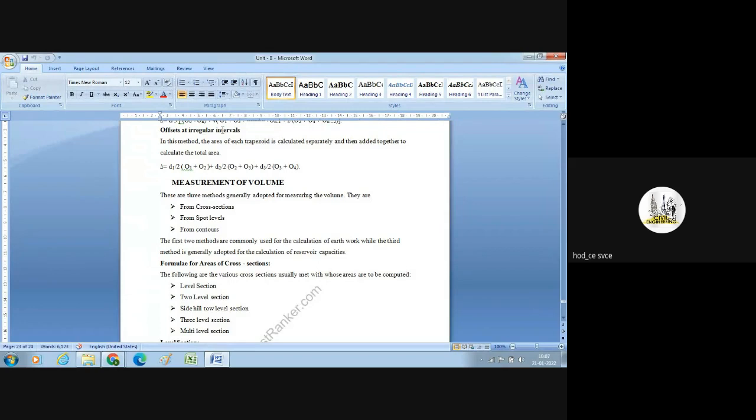Murli has taken one of the images, I mean a screenshot, right? So what we are doing there is, we are going to calculate the distance. If you have the AB line, instead of that AB length, we have to take the horizontal distance, that is, the departure distance from the meridian itself.